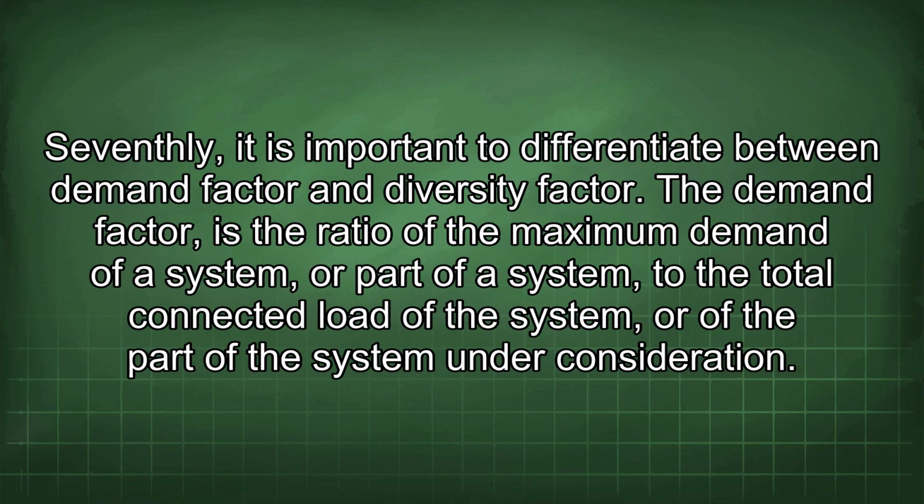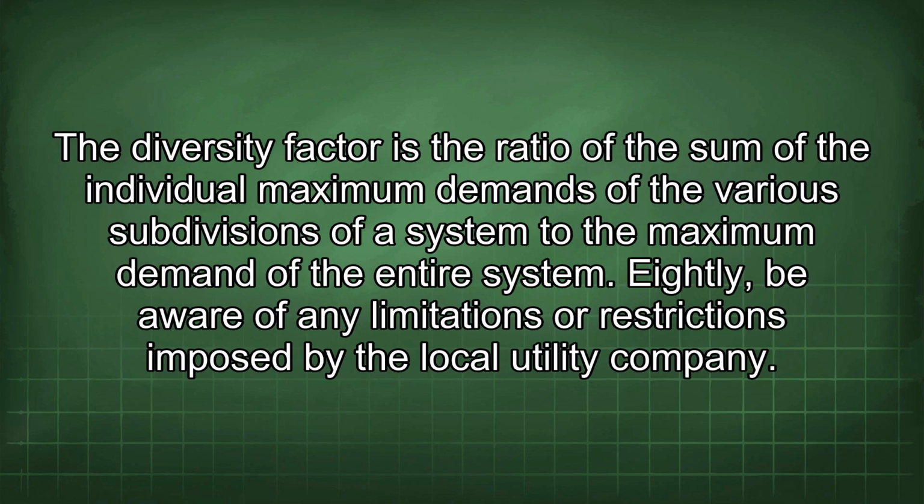Seventhly, it is important to differentiate between demand factor and diversity factor. The demand factor is the ratio of the maximum demand of a system or part of a system to the total connected load of the system or of the part of the system under consideration. The diversity factor is the ratio of the sum of the individual maximum demands of the various subdivisions of a system to the maximum demand of the entire system.